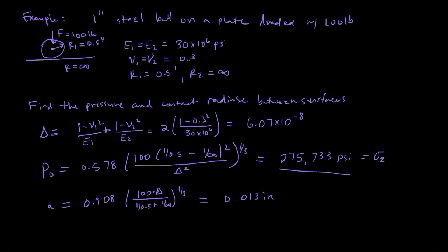Okay, so it's pretty interesting that we can calculate these and get a feel of what that downward stress, sigma z, is, and we can relate that to our material properties and make sure we're where we need to be. If this is for an application that is cyclically loaded, then we could use our fatigue analysis to find out the life. But this is a way where we can actually get real numbers that we can use for design.